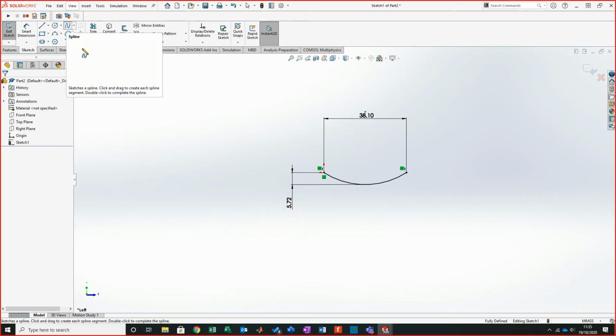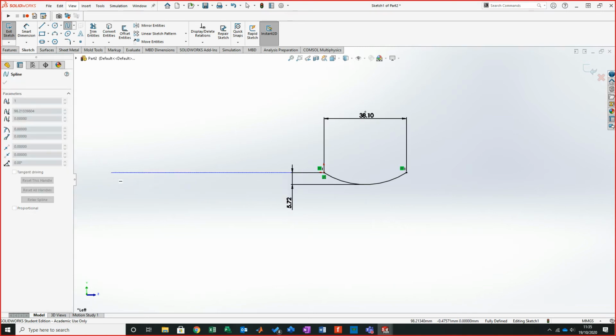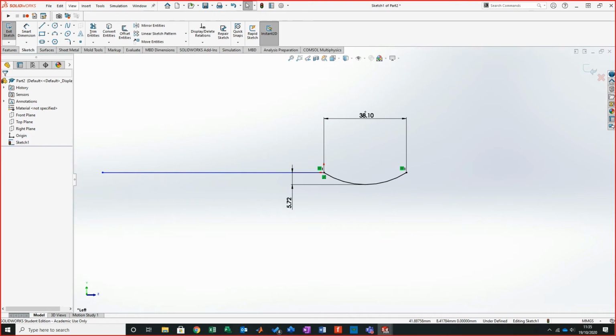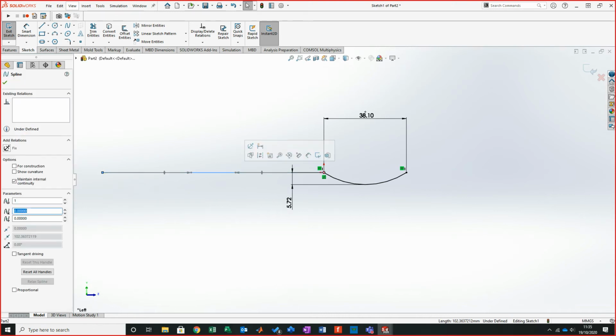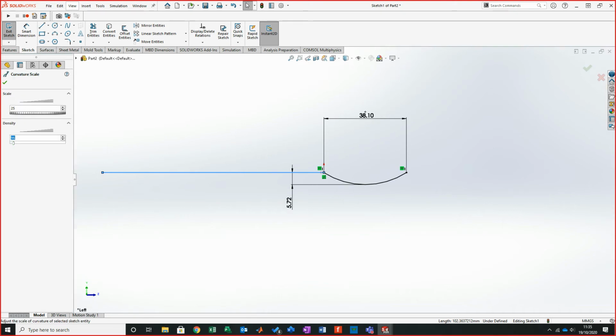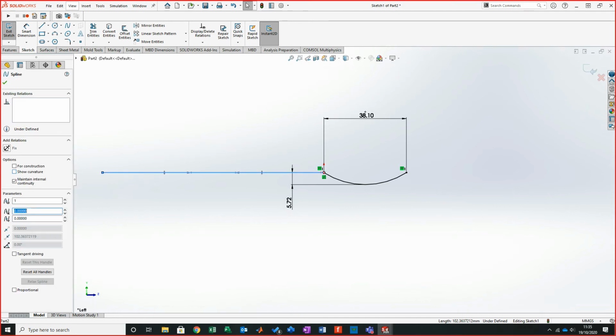Now I've gone to spline. Somebody told me over the summer that this has now become very easy to use. If it has, I'll be so gutted. Because, not to be a pain, but it is really useful to learn how to use this. So I clicked on there, and then all I'm going to do is click select. So I'm on the 3 points here. So left click on it. Now, we've got show curvatures. What else have we got on here? I'll turn off my curvatures actually.